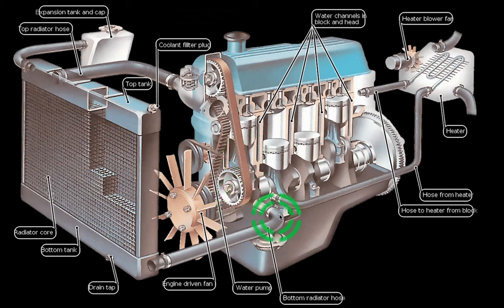Because the thermostat is only blocking that. So that's all they could understand about the thermostat. So what happens is that when you do that and you run your car, you get amazing results. You see that your temperature is not rising at all. Remember when I first told you that the thermostat helps you in reaching that temperature as soon as possible? Now that purpose is completely defeated. So your temperature does not rise. You keep it running, let's say for 2 hours, and you're still at 60 degrees Celsius. So you're like, wow, that's nice, my gauge is not rising, it's low.